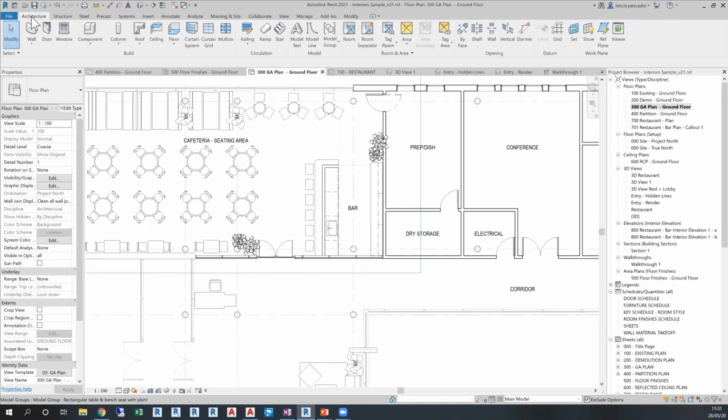Revit LT will also have libraries which contain components from all the disciplines, so you get the full library out of the box with the LT. The LT version won't have worksharing capabilities and design options as well. Revit LT will be a basic version of Revit.